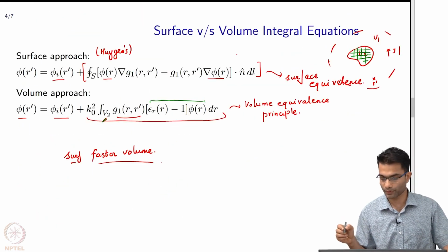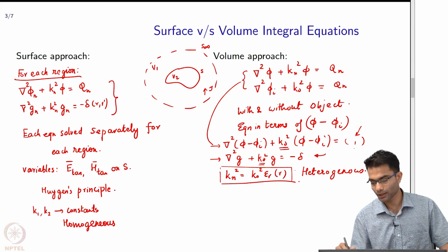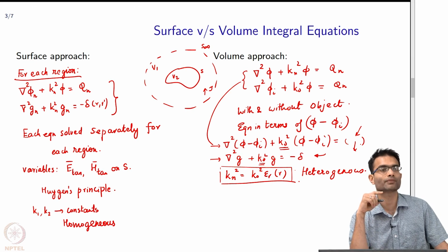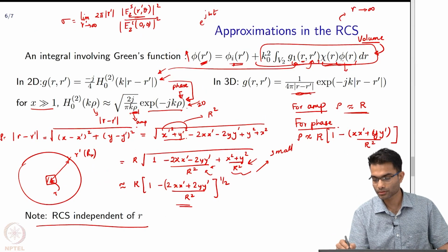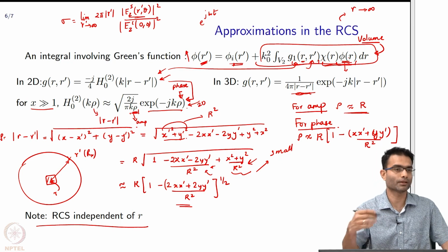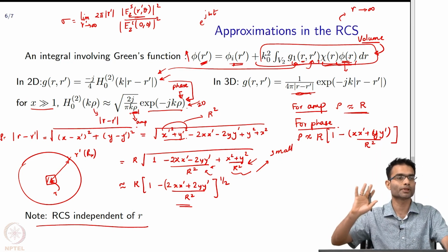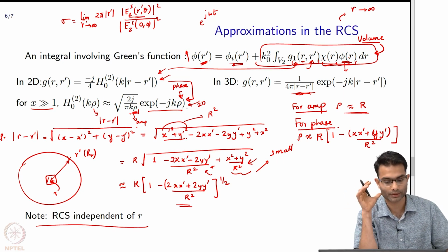If you look back at our equation, the incident field appeared over here. Depending on the value of the incident field, the current inside the expression got set. So implicitly the solution that I get depends on which angle I am illuminating the aircraft from. That is why it is a function of theta I.